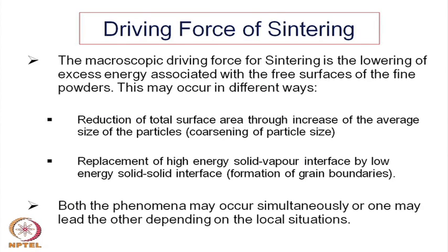Now, why do the materials get sintered? That means, why do the pores get removed? A loosely bonded compact, sometimes referred to as a green compact, without heating to high temperature has very low mechanical strength and is not useful for practical purposes. But when you heat it to high temperature, you get a very sound, mechanically strong, non-porous material, as good as any other materials like metals or plastics. It loses its porosity, and the particles get bonded together and a strong bond develops.